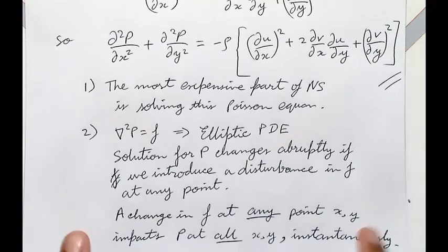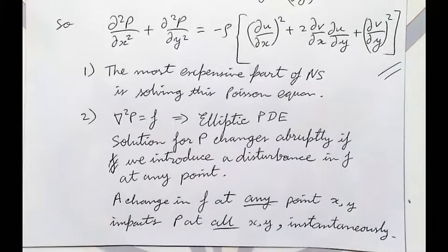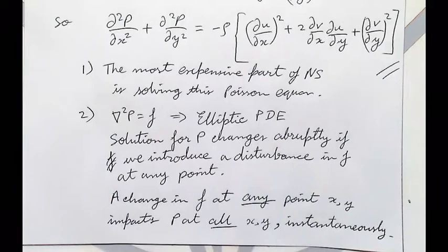This is a big problem. You will see if you start solving the Navier-Stokes equation, and you have a bug that messes up one point, the entire solution gets corrupted because of that one point. Compressible flow is slightly more forgiving, because the mess up there will take some time to propagate. But that adjustment is instantaneous in the incompressible solution. More questions?